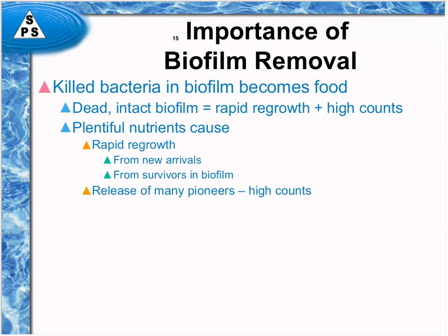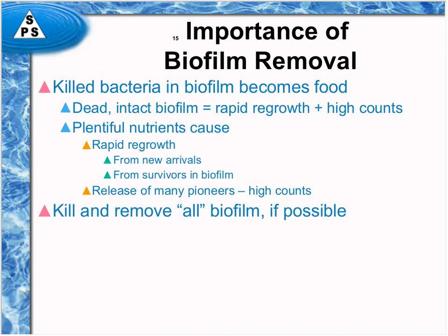And what happens in the presence of all this extra food? Remember what happens with the pioneer cell development in the presence of high levels of food. You tend to promote the formation of pioneers because they're sensing high nutrient levels. And whenever you get lots of pioneers released into the water, what do you get? You get high counts. And so that's why usually within about a week or so of an ineffective biofilm sanitization process, you got high counts again.